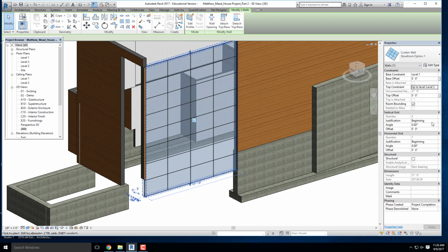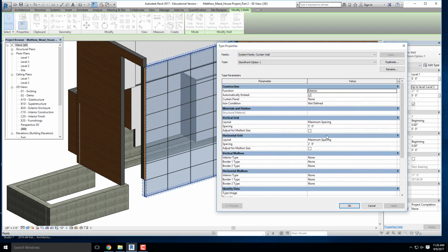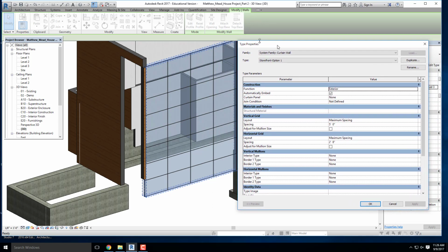8 grid. Keep in mind that as you're doing that, it doesn't necessarily mean that the spacing of these modules is exactly 5 foot by 2'8". You're just saying that it doesn't matter what the size is, as long as it's not bigger than those dimensions that you're providing. So you're creating a group of parameters which your model will live by, or that particular storefront will work under. Okay, so from here, let's continue down on what some of our other options are for these type properties.